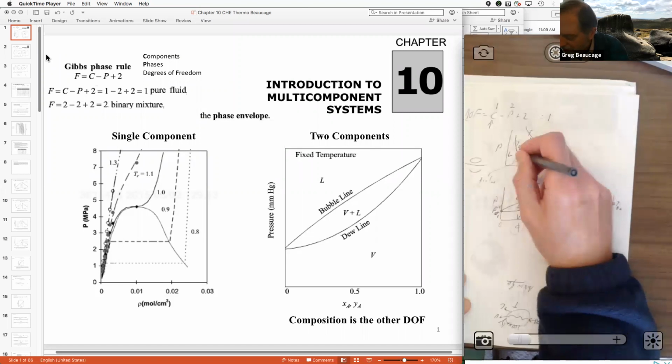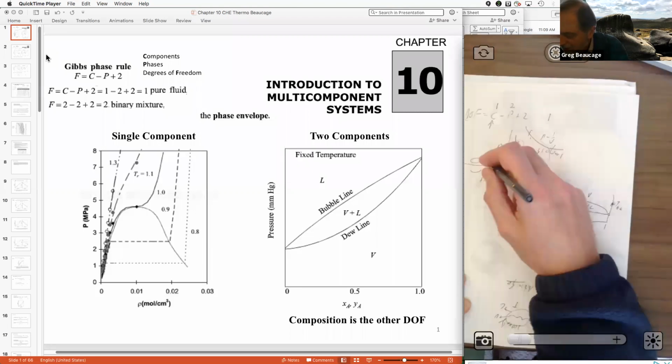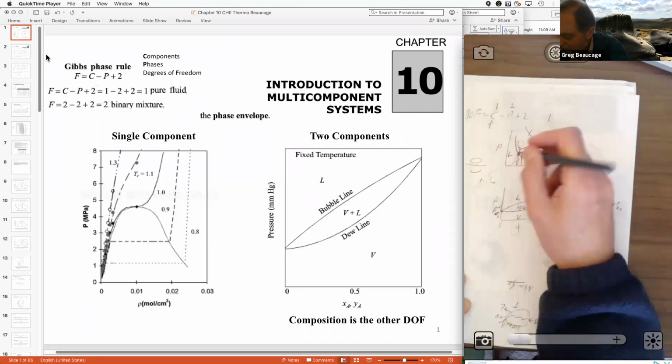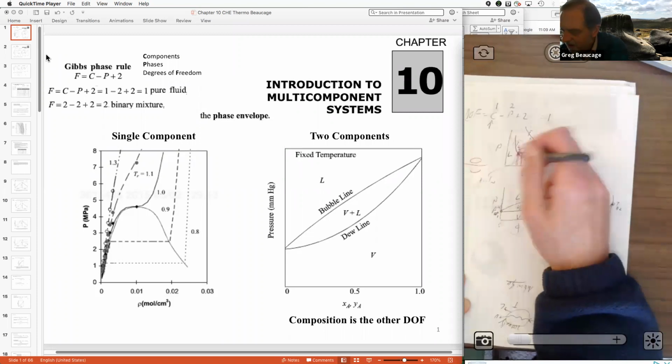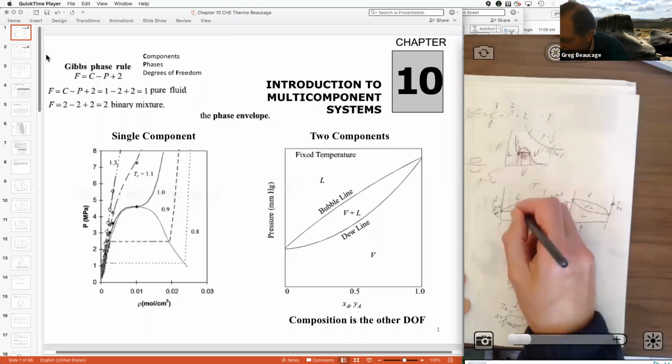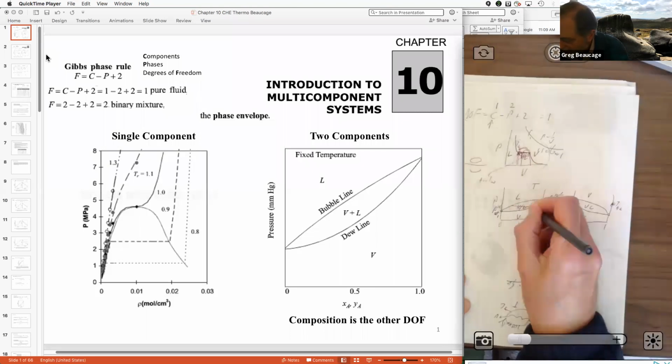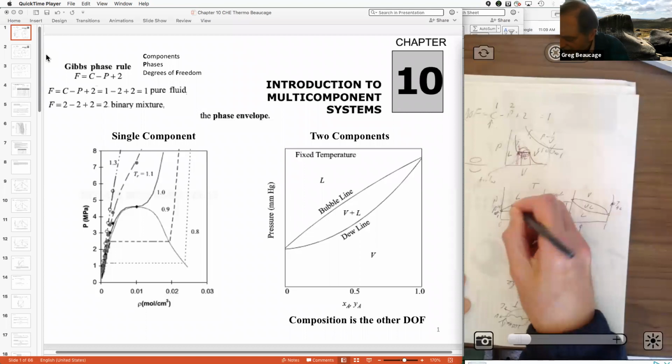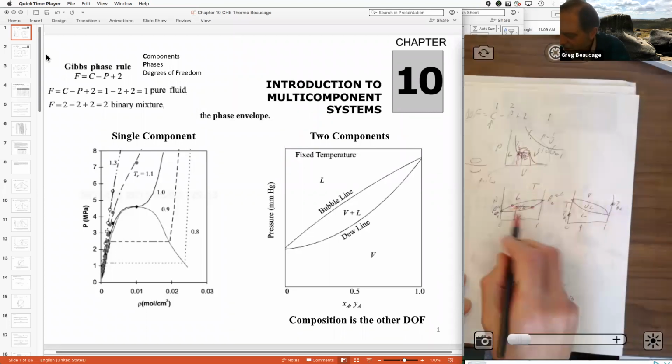Right, so if this was all the way over at the saturated liquid point, this would be the entire line, that would equal 1. And then if it's at the vapor point, that line would be 0, so it'd be 0 over the total. And so the tie line rule works here also. It's the same kind of thing. So you're going to have this kind of tie line, and you have some composition in the middle. So you have a mixed phase of liquid and vapor.